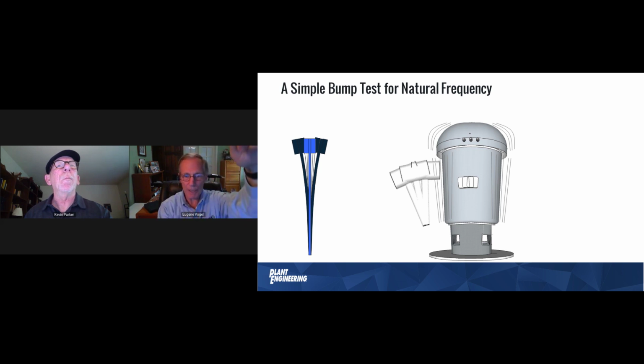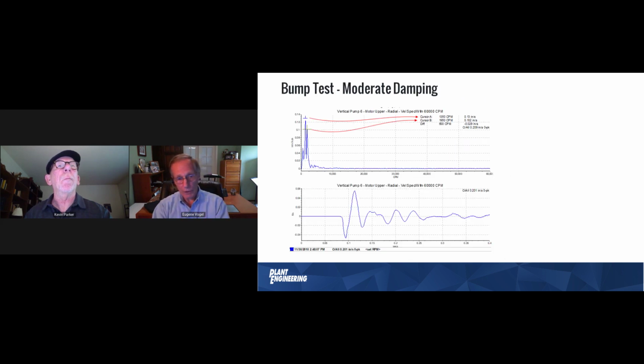Well, that pencil would draw a line vertically, if I turn this up on end, that looks something like that bottom plot. That's how it moved. You can see where the hammer hit it, and it went down, and then it vibrated back up, and eventually the machine absorbed that vibratory energy, and it quit vibrating.